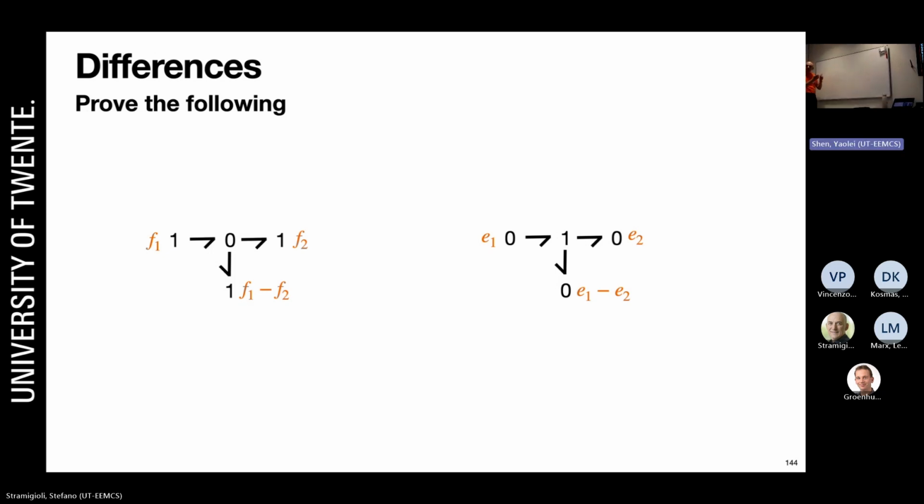I can give it a representation, because a one junction represents the flow that all the bonds attached to it have or need to have. In the same way, a zero junction I can call an effort junction. I could say that it represents that force, because I know that all the bonds have the same effort.